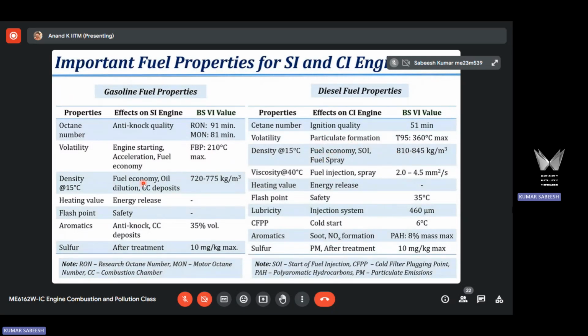We already discussed that for gasoline, we meter fuel on a volume basis. Metering is the process of controlling the fuel volume for each engine operating cycle. So we have an injection system that allows only a metered, precise quantity of fuel into the engine for each operating cycle. Because we meter fuel on a volume basis, any variation in density will reflect in the mass of the fuel that is injected into the engine cylinder. You are controlling diesel engine power output by varying the injected fuel mass.